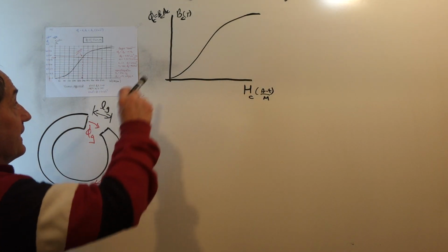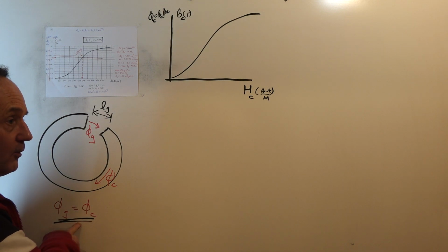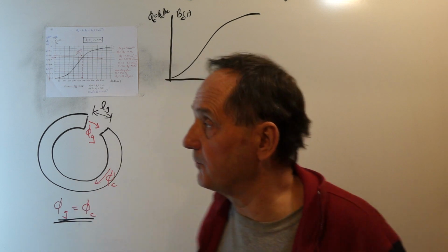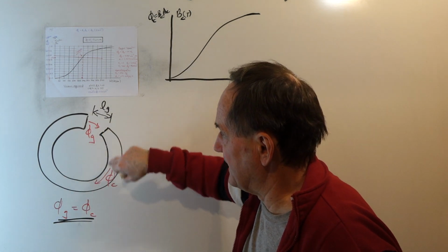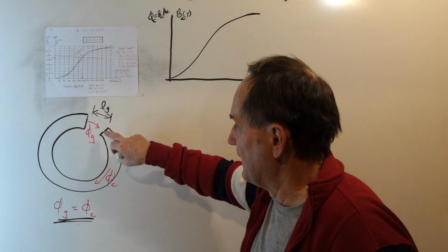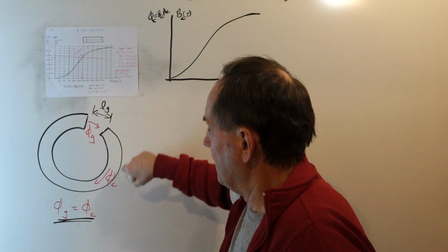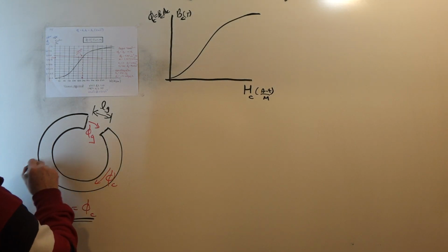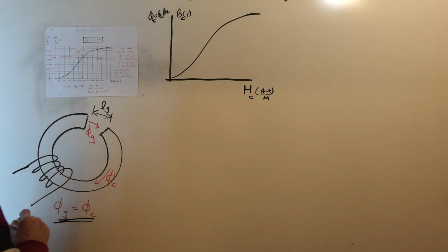Now, because of the nonlinear nature, we didn't have a good analytical way of solving this like we did initially when we assumed and was given the permeability of the core material. In general, we don't know what that permeability value is because it varies with the strength of the magnetic field intensity in the core. So we wind a coil around the core as before.